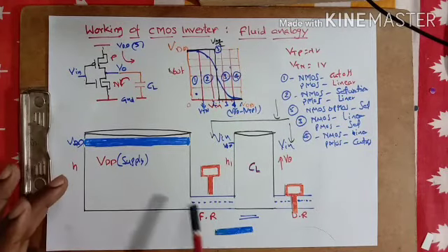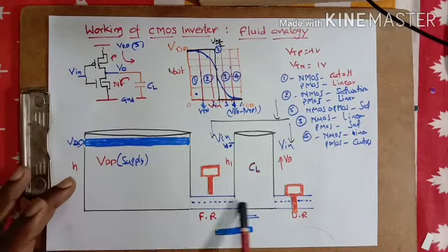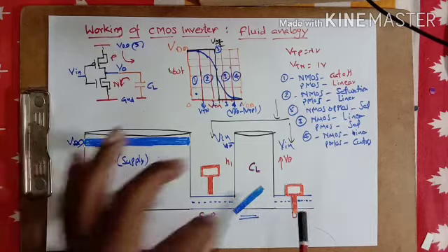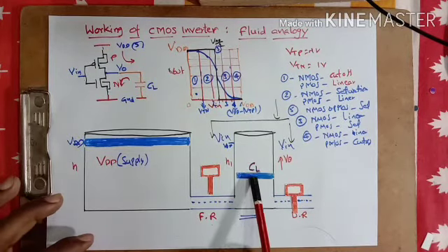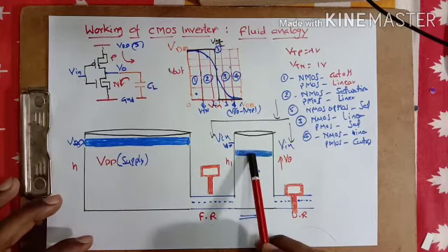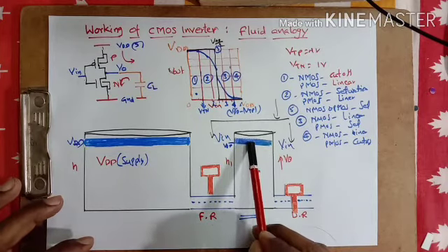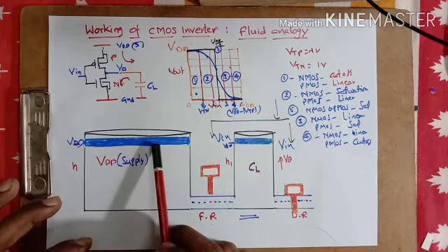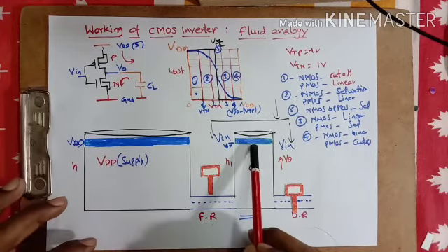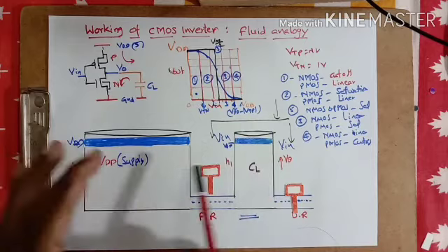So what is happening here? There is a flow of water from here, which keeps on filling the bucket. There is no outlet, so it is not going out. The water level in my small bucket slowly fills, and I am giving enough time, so it comes to the maximum height, which is the same as that of my bigger tank supplying it.